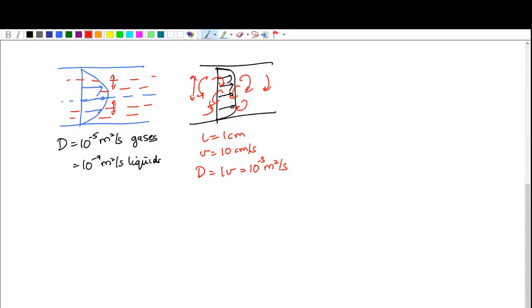And because of that, as you can see, this dispersion coefficient due to a turbulent flow is actually much larger than the diffusion coefficients you can have here, especially in liquids. In liquids, the diffusion coefficient is very, very small, and it will be nearly impossible to have mixing in liquids over reasonable time scales unless you have dispersion.